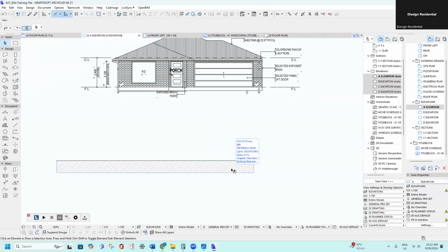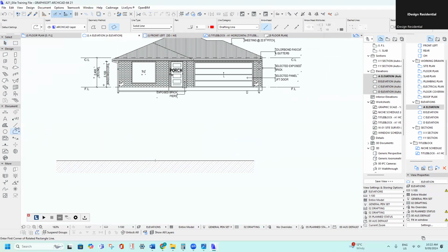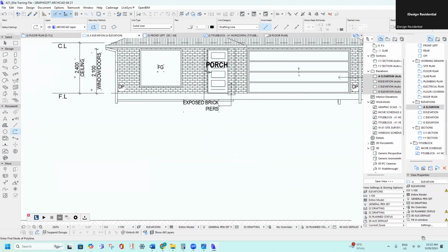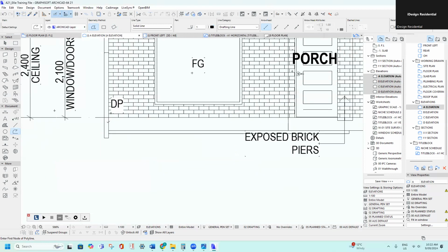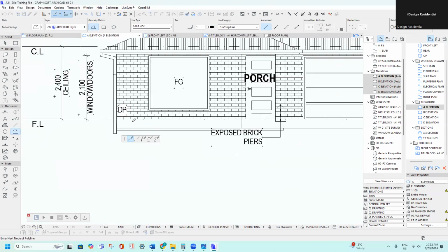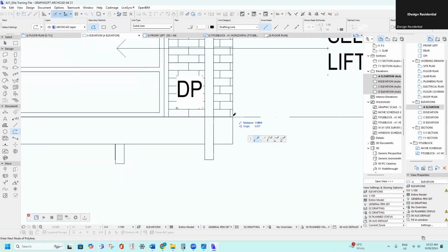What I like to do is, if there's no fill in there in a line at the moment, you click the line, click the polygon, click on black. You can keep it an ArchiCAD layer because it's not going to show on any other plan. So there's no issue with that. I like to draw at the bottom of the brick, where the top of the slab is.